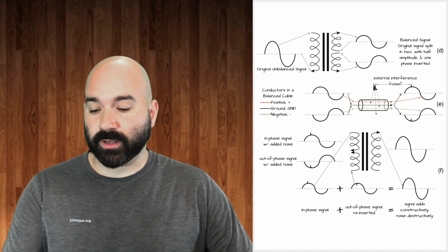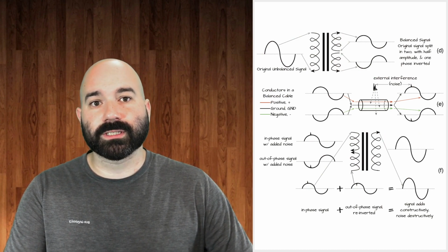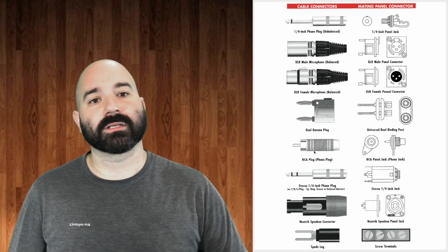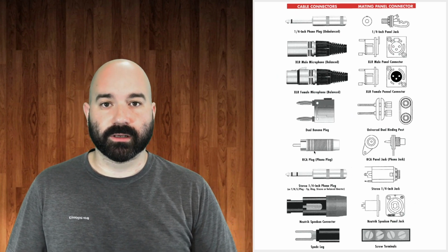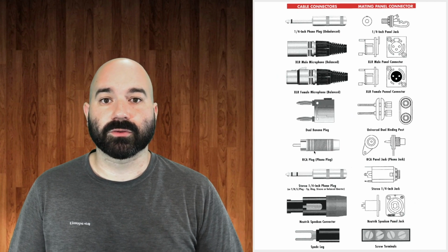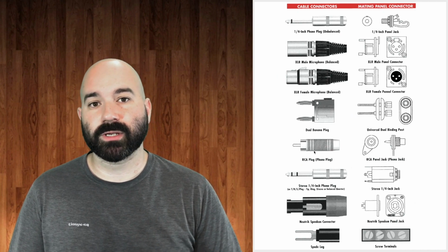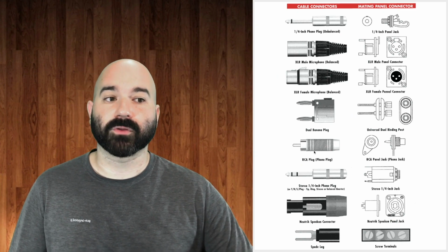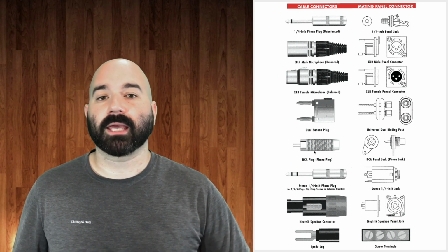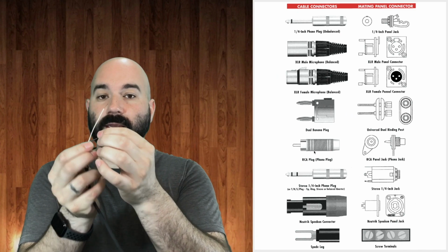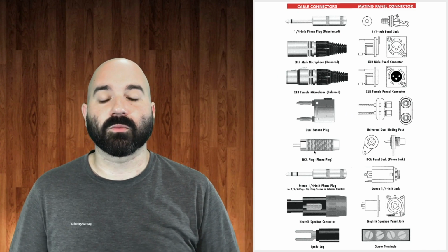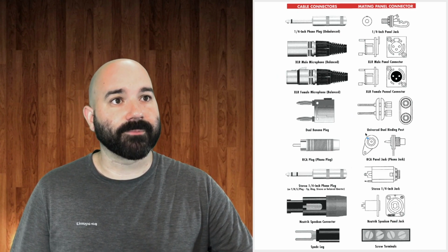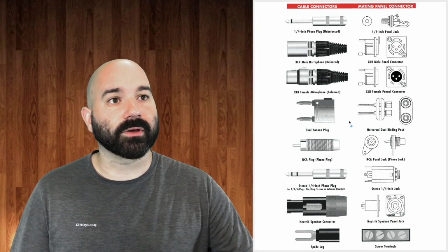And so now we're going to move on to our next section, which is types of electrical audio connections. And this is where we can start to talk about the differences between conductors. And I made a video that goes through the different types of connections. But again, just to reiterate before we go into that, for a balanced line signal, you have to have 3 conductors. And without taking a cable and breaking it open and physically looking within them, how do you know whether or not it has more than 2 conductors? And most cables you can tell by looking at the ends of them. So we'll go down this list here and I'll just show you briefly.